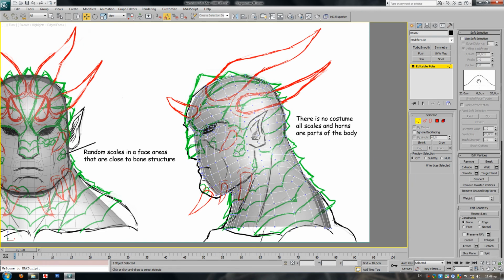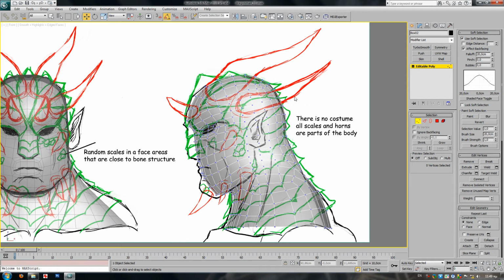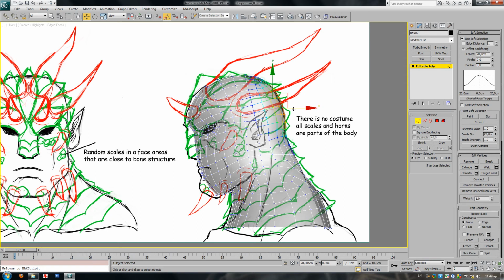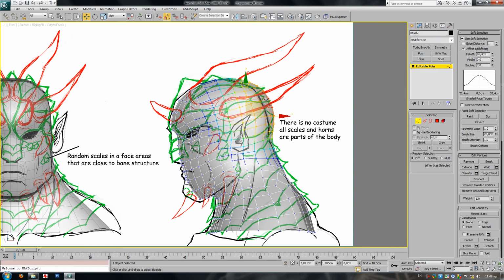We're just gonna turn on soft selection, and now when I select a vertex, you can see that some colors appear. Red represents 100% of my action, and blue 0%. Well, white is 0, but blue is colder, red is hotter, and by using this I can move things proportionally. So I can make his neck thicker, his head bigger.